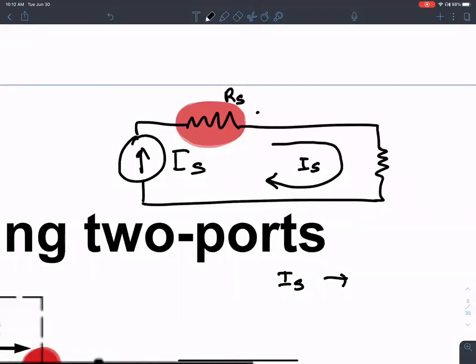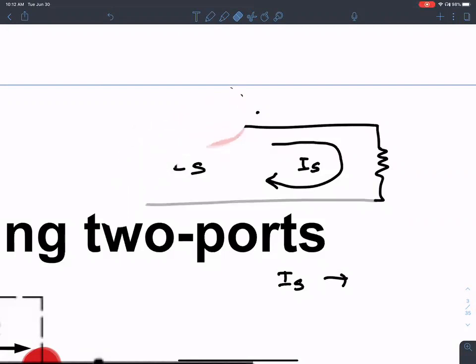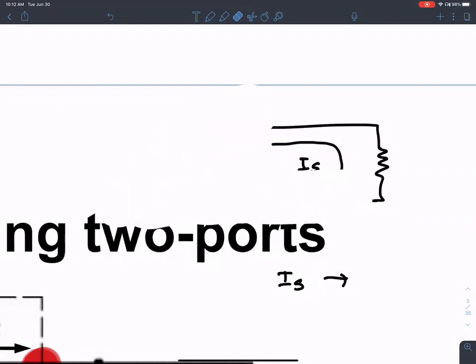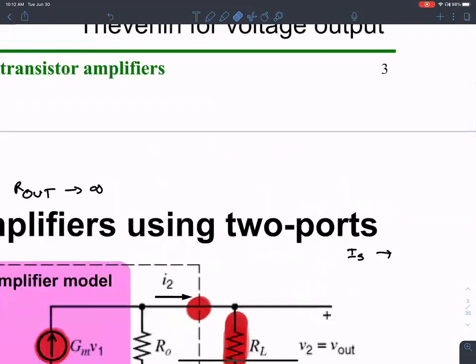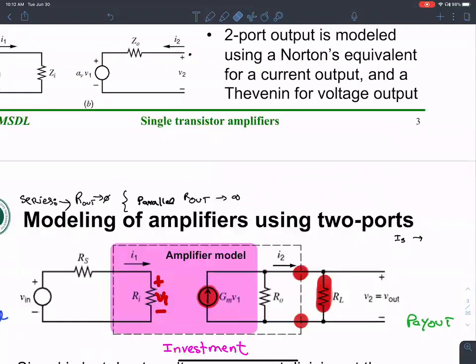That was your question, right? If I had a current source with a series resistance, then the idea was that we may not have a signal loss. Well, that's not the case. As a matter of fact, even with a current source in series with a resistance, we do have a signal loss. But the Norton's equivalent, one way to abstract away the operation of a black box, is to think of it as a current source with the equivalent resistance.